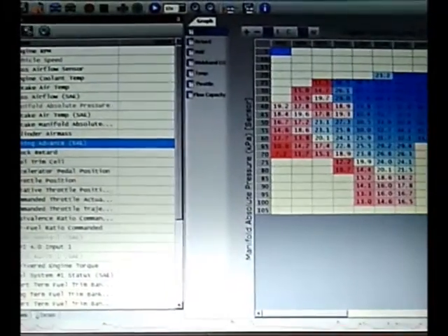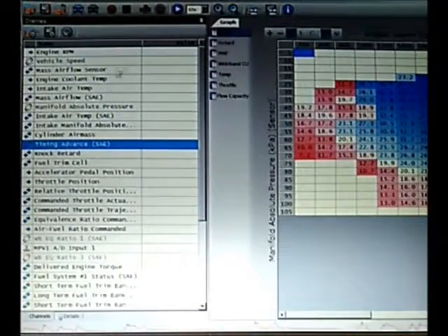Notice how it says SAE in brackets. Anything that says SAE, which stands for Society of Automotive Engineers, means that parameter, that PID, is universally supported. It has to be supported. It's kind of like standardized, like USB or something. So anytime you see that, you'll know with confidence that it'll be supported. So you don't have to worry about whether your car supports it or not.